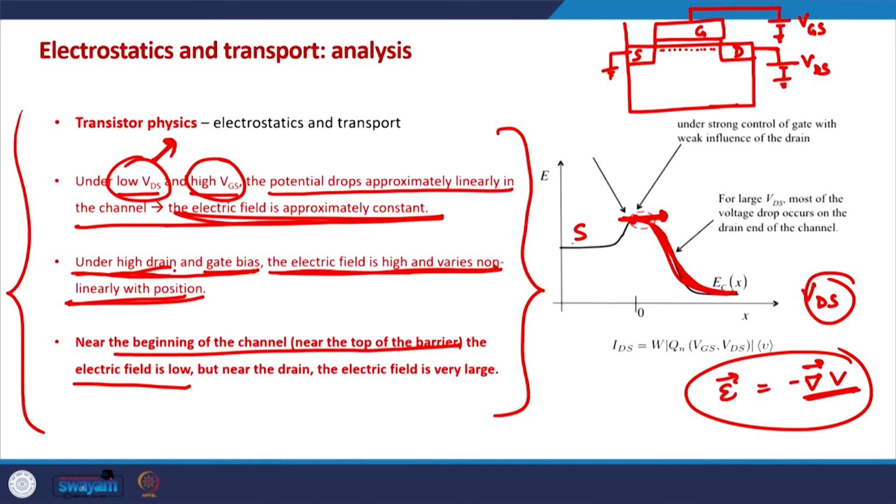Let me take a moment and summarize what we have seen. We have seen that the MOSFET is a barrier control device. We have seen various IV characteristics of the MOSFET. We have also derived, very qualitatively, a glimpse of how the IV characteristics of the MOSFET look, in which we considered that the current going from the source to the drain side is ILR, left to right, and the current from drain to source side is IRL.